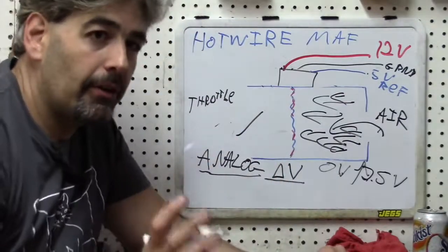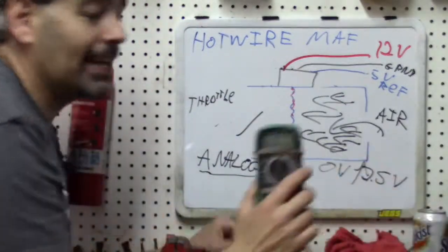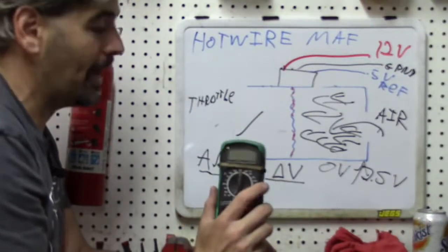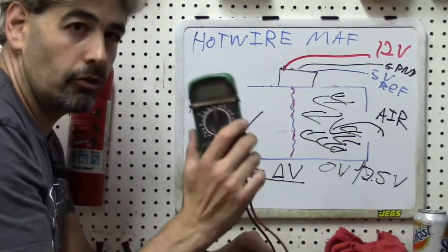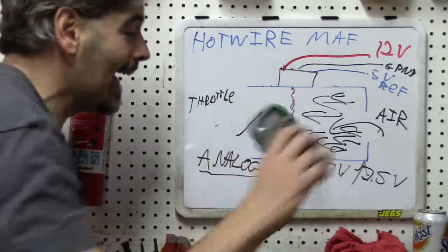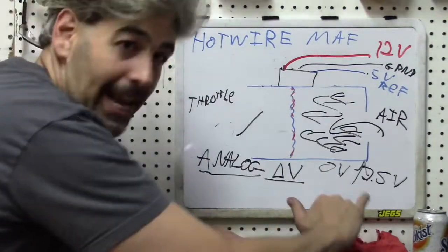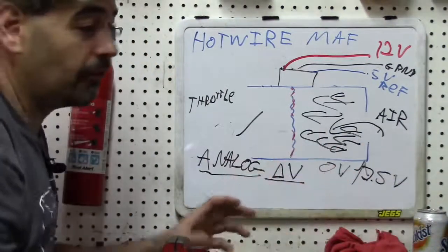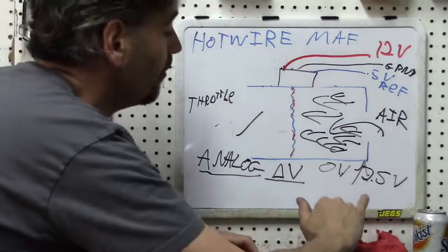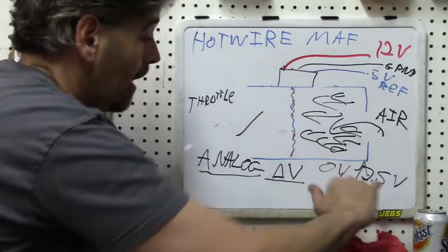Again, very, very similar to doing a throttle position sensor. And it is not the optimal way of doing it by any means, but you can use your traditional DVOM like many of you guys rely on. And of course, I rely on as well. But also on a scan tool, and we'll show all of this when we actually play on the car. On a scan tool, you will usually see that voltage reading available.